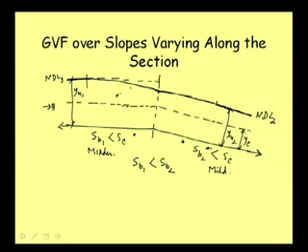Well, this profile as it is occurring over mild slope, so its name if we try to give, it will be M. And then let us see zone wise. Zone wise, it is between critical depth line and normal depth line. So, in zone 2, this name will be M2 profile. The name of this one will be M2 profile. Okay.